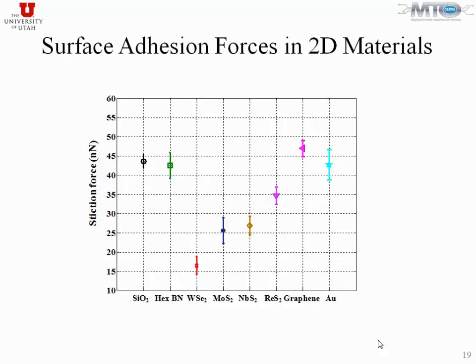And two-dimensional materials have the added advantage that, for example, if you look at graphene, graphene has this close-packed carbon layer, and how much energy does it take to pluck one of those carbon atoms out? And if it is relatively high, then these would be good contact materials because they're completely close-packed, highly packed and closed structures. There are no dangling bonds essentially, other than the hybrid pi bonds that are not really dangling, but they can cause problems later on, but they're much better than what you get on metals.